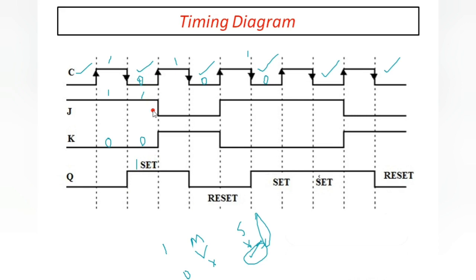So to understand this operation, J1, K0 and slave is activated here. To understand this operation, you need to observe JK flip-flop. J1, K0 means output 1. Okay. So output is going to be continued until next 0, because at the next 0 at this point slave again changes its values.